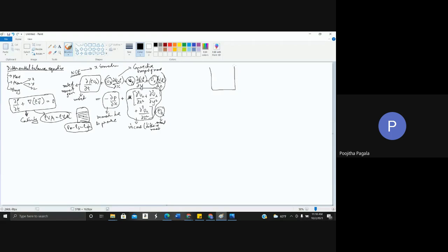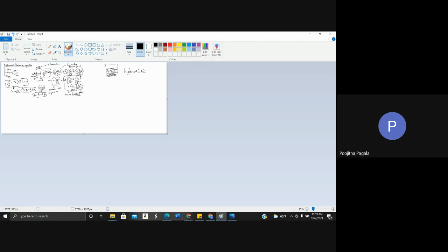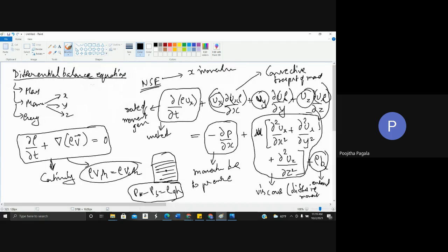Now I have a tank where there is no motion, that is hydrostatic. So there is no flow at all. So ux is 0. If ux is 0, can you tell me which of ux, uy, uz are 0? Can you tell me which terms of this equation will become 0 now? And I'm writing the momentum in the y direction.